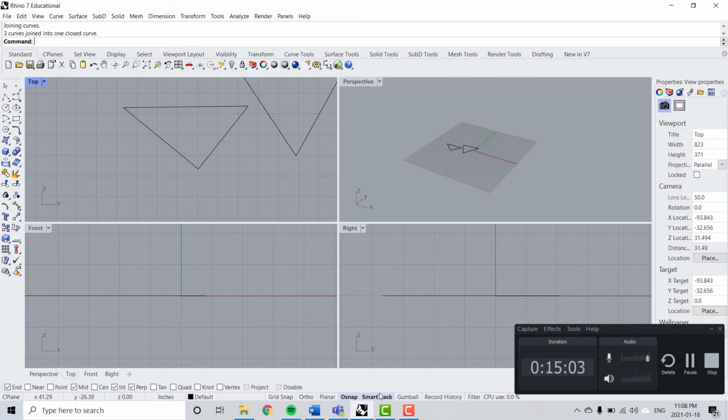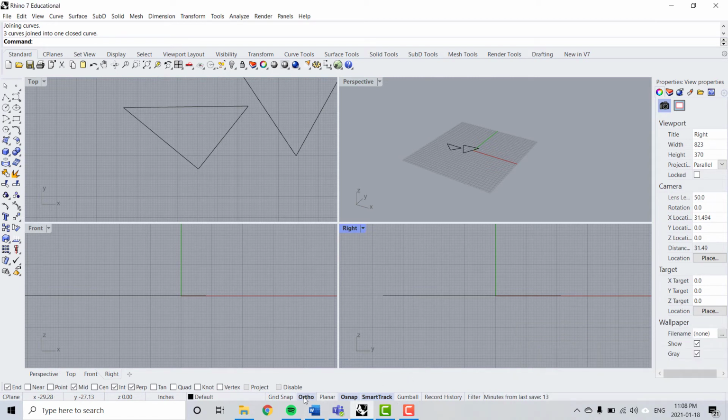All right, so next on the bottom here is the ortho command. I like to have that checked off when you're drawing floor plans, especially if you're doing the grids. So notice I'm going to click here. And then it's restricting me to drawing vertically, horizontally, so it's forcing you to stick to the X and Y axis. And it's really good to have when you're drawing rectilinear objects, like a grid plan or that kind of thing. So you can always check this on and off.